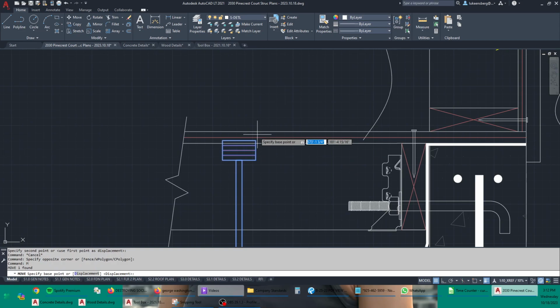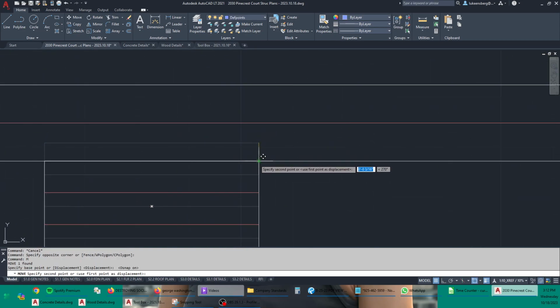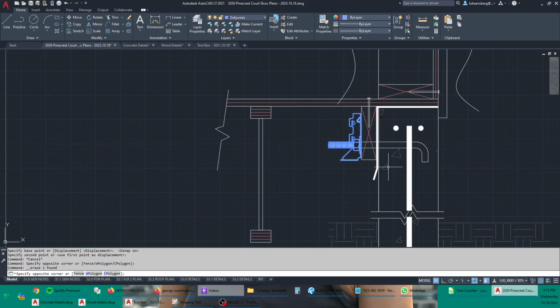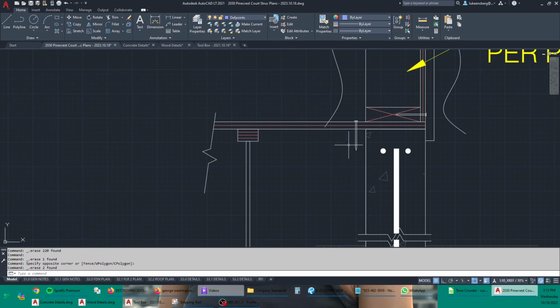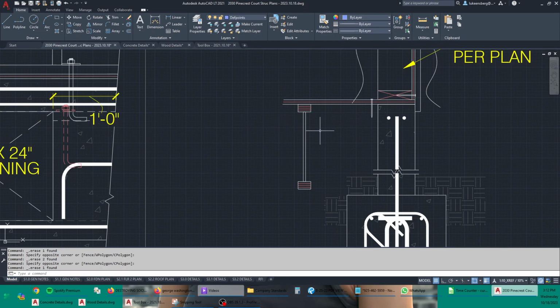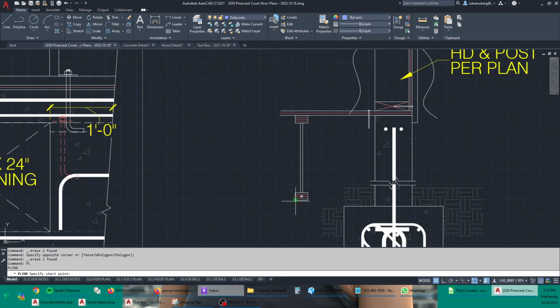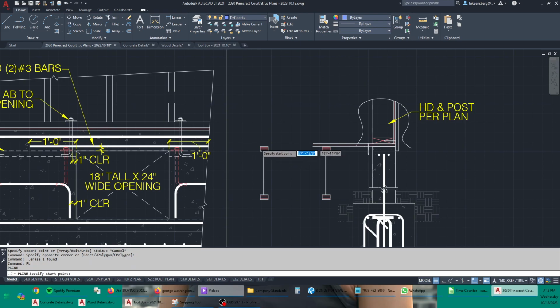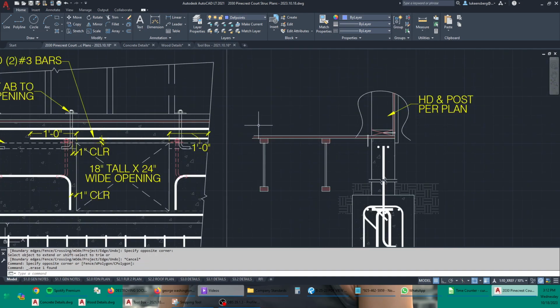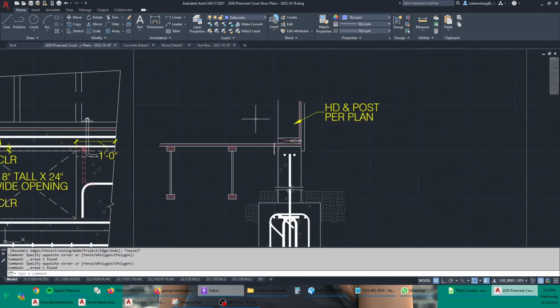I move that up like that, and then I use snapping to grab that corner and bring it down to there. So now the joist is placed right below the floor sheathing. Get rid of this stuff, don't need that, goodbye. This can go away, and the joists are going to be 16 inches apart. So I'll draw a line here that is 16 inches long, and then I copy the joist over like that to that end of that line 16 inches away. So these are now 16 inches apart, and I want the floor sheathing to come over just like that.